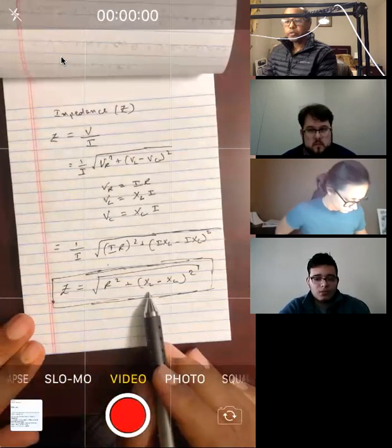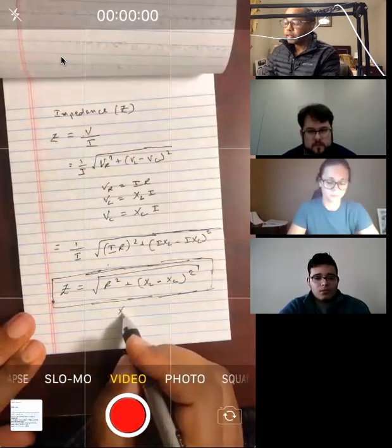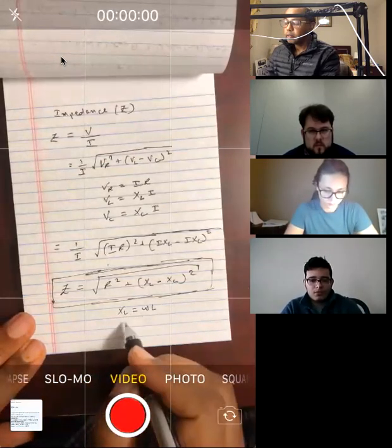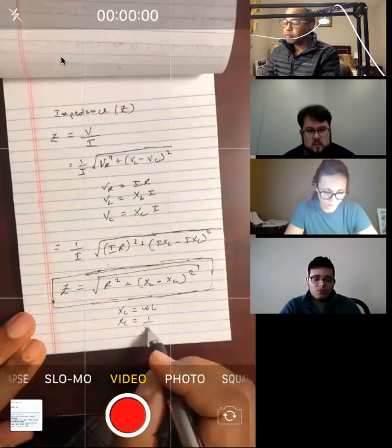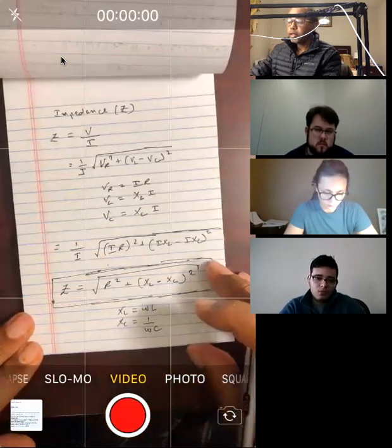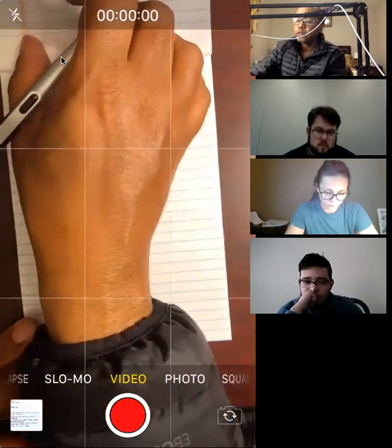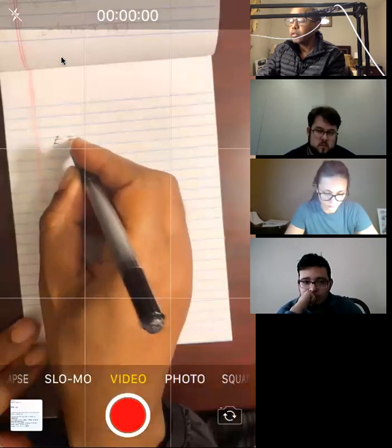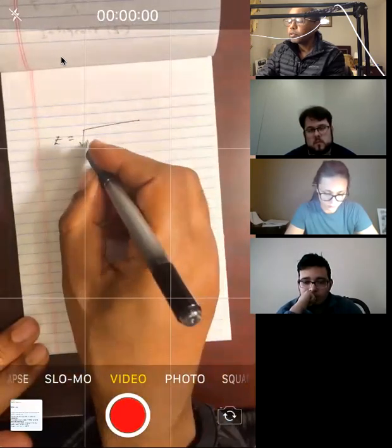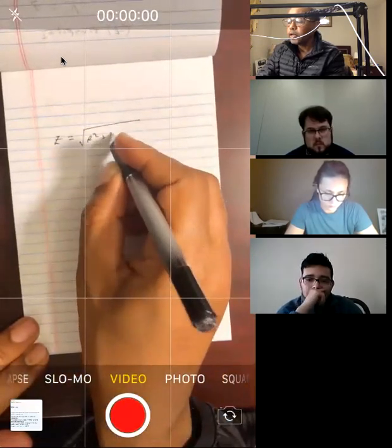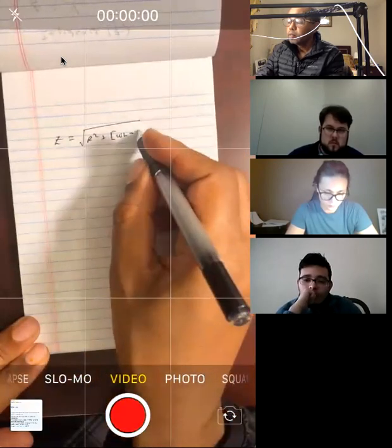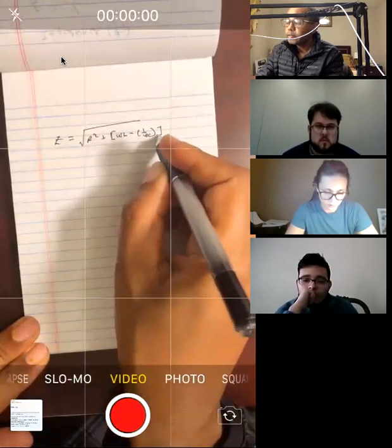Or we can express this in terms of frequencies. You remember, we have XL equals omega times L, XC equals 1 over omega times C. If you put that in, we get the following expression for the total impedance of the circuit: Z equals square root of R squared plus (omega L minus 1 over omega C) squared.